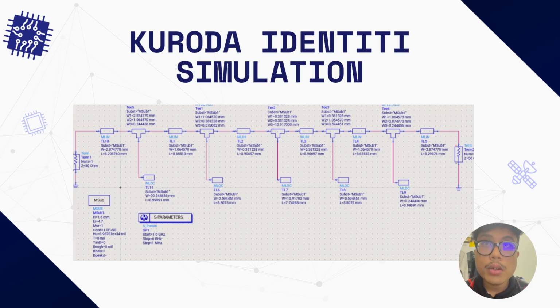Here, what we did using Richards transformation, we convert series inductors to series short stubs and shunt capacitors to shunt open stubs. Then we apply the Kuroda second identity to convert each series short stub into a more practical shunt open stub configuration. Okay, the transformation introduces unit elements and results in a cascade of transmission lines and shunt open stubs, which is exactly what we need for practical microstrip application.